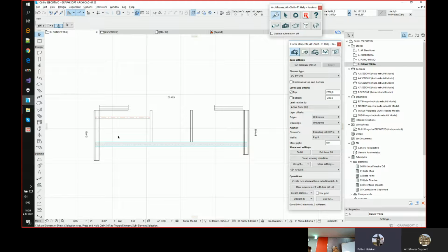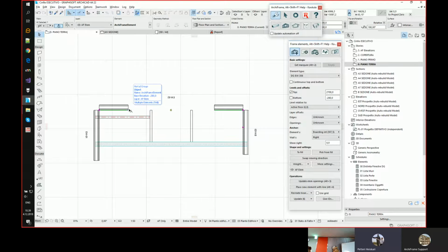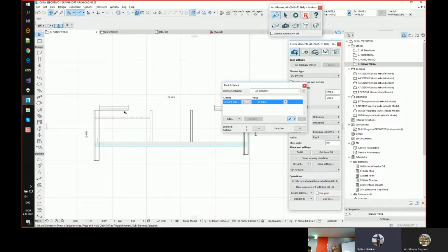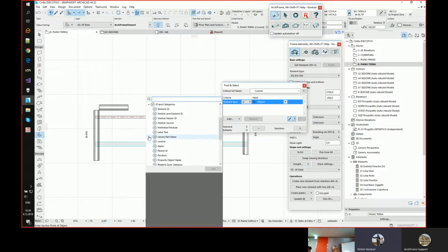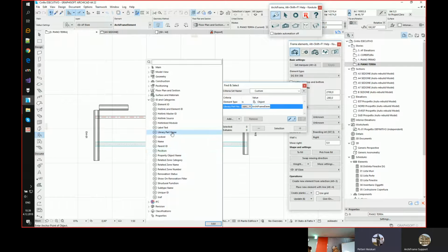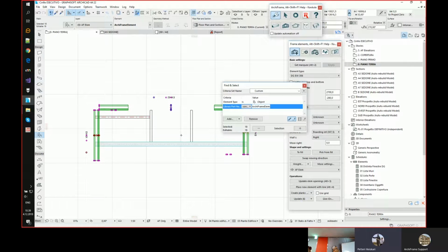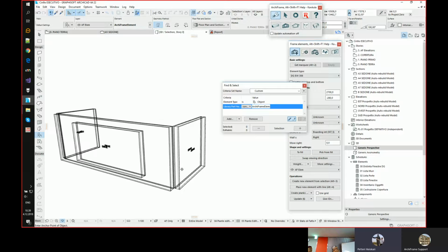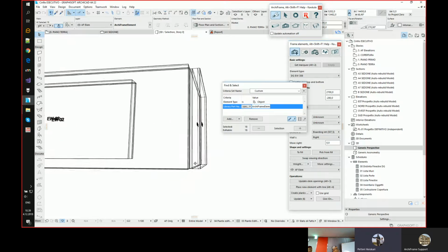And the idea is that we have a unique ID for each piece, so we have different IDs for different walls. And then perhaps I'll show only these ArchiFrame elements objects in 3D. So I'll make this show selection in 3D. And first, let's apply some layer offsets. I'll rotate so you will see what happens.